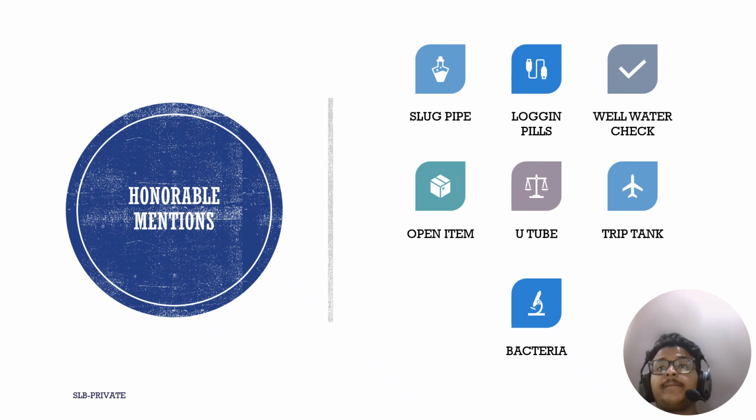Well water check: we need to check the water before entering any rig or any operation to make sure our mud can work with it. For example, chloride needs to be lower than 400 and calcium needs to be lower than 600. If not, it's a problem. We cannot use the water for our mud. We need to contact Aramco to provide us with new water.